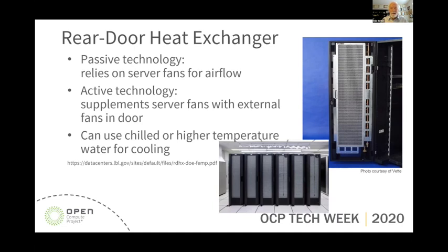We go to the active rear doors or the ones with fans when our heat density is higher and we need the greater output, especially since we're trying to achieve the cooling with warm water temperatures.